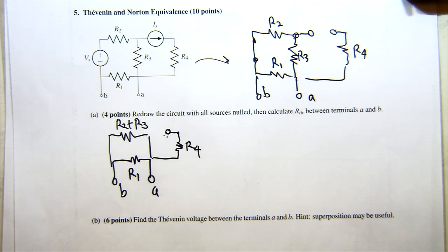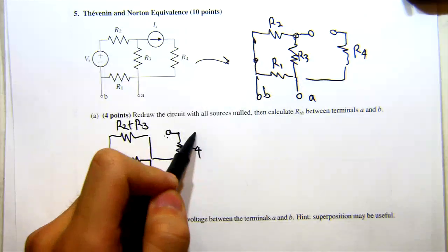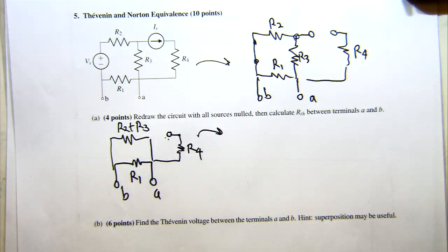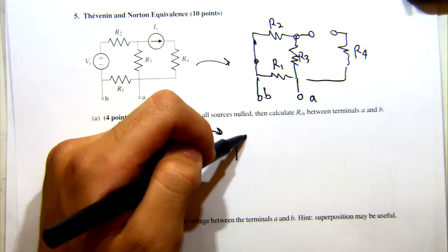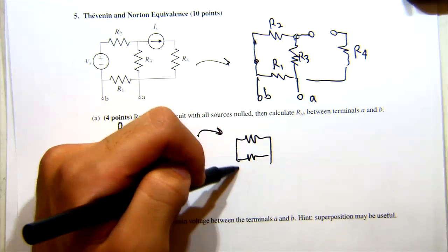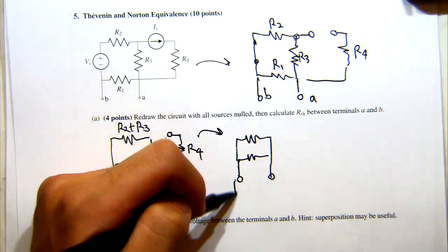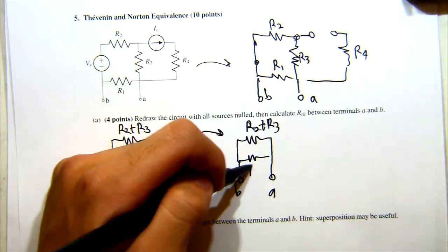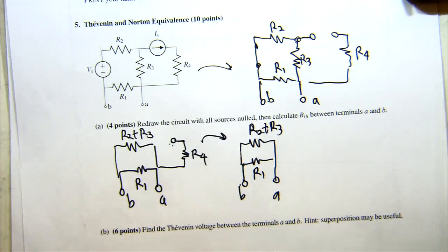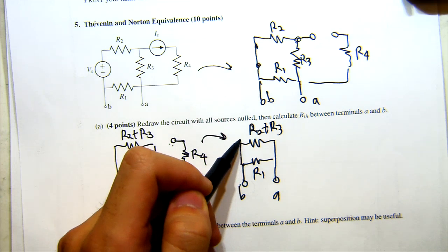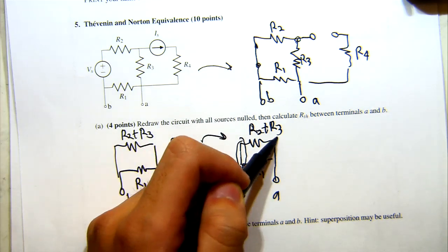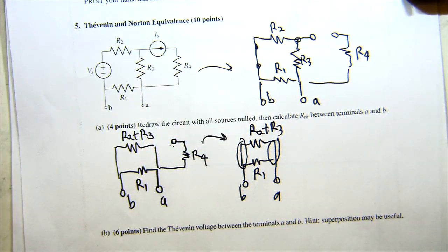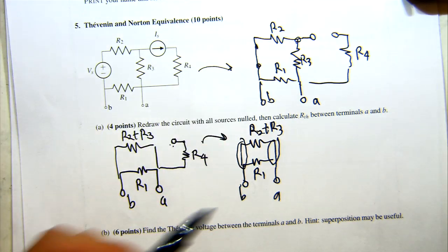There's a question? No. So the next step we can take is to redraw this and remove that resistance. In this case, what we really care about are these two resistances right here, where we have R2 plus R3 and then R1. So finally, we're left with two resistors. We can note that they're in parallel. If you note right here, there's this node that they share, and then there's this other node that they share. So what we can do is replace that with the parallel equivalent.